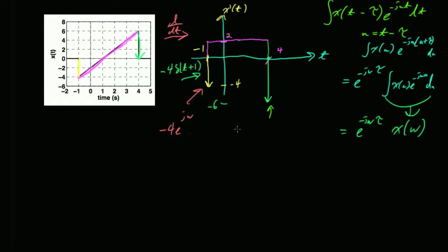Okay, let's do this impulse. What's the Fourier transform of that one? Minus 6 e to the minus 4j omega. Okay, good. And now we need the rectangle. What's the Fourier transform of that rectangle going to be? It's going to be a sinc function. So, plug and chug. Don't make it harder than it needs to be.